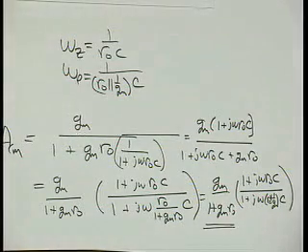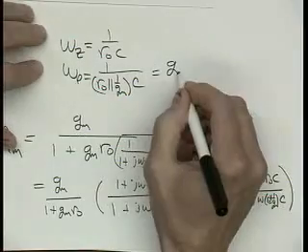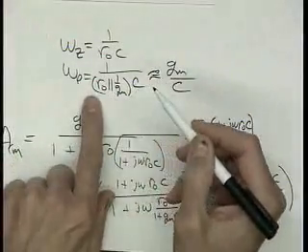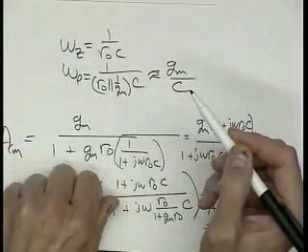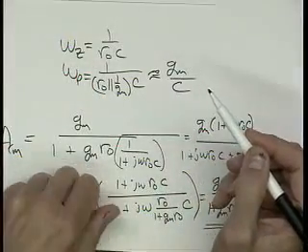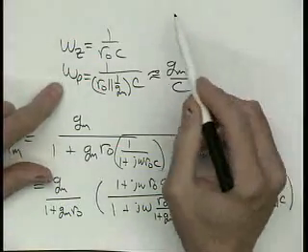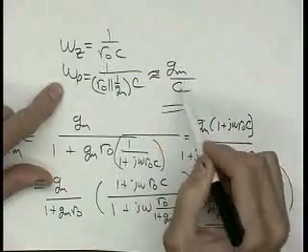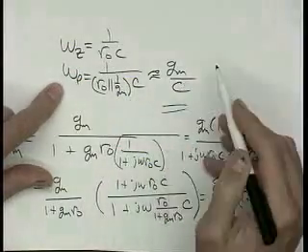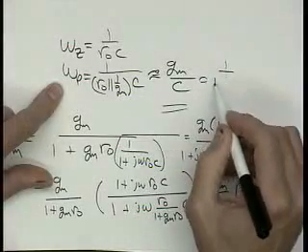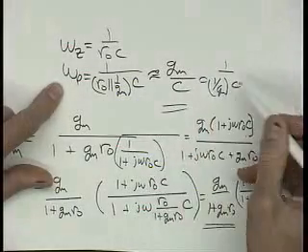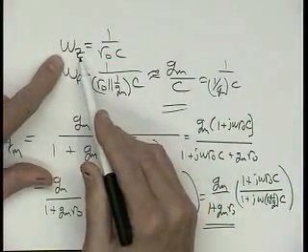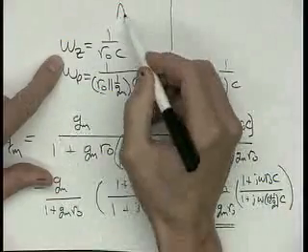Okay? So this is equal to gm over C approximately, right? Because 1 over gm is much smaller than R0. So what's going to happen to this circuit? We're going to see this pole is clearly at a much higher frequency, which is equal to 1 over gm times C. In other words, look at that. The pole is at a much higher frequency, so the zero is at a much lower frequency. So we're going to start plotting our common mode gain.